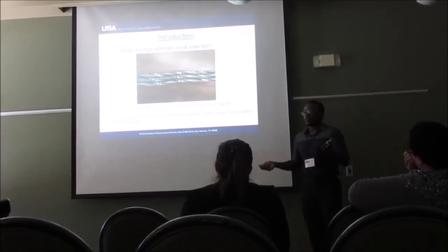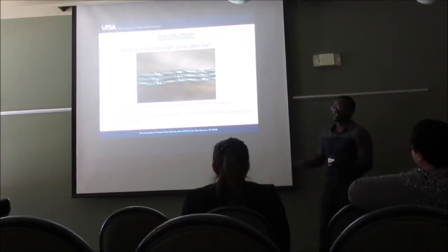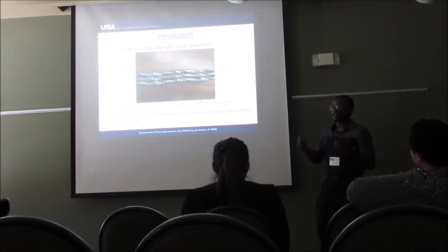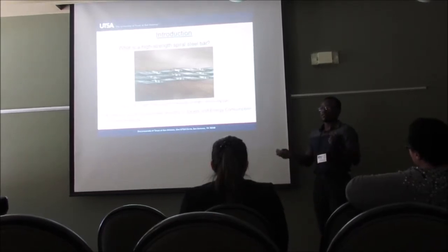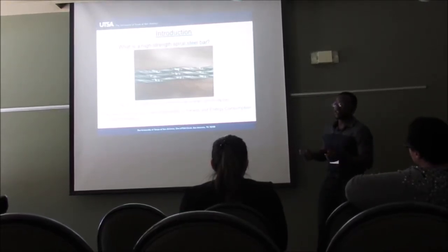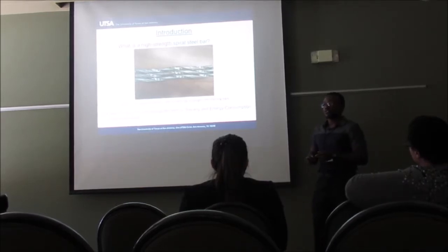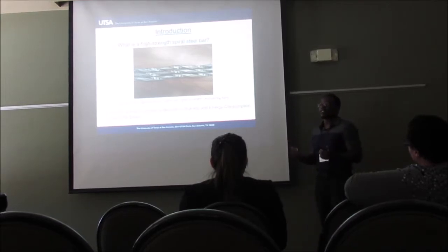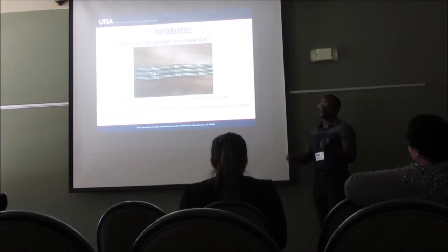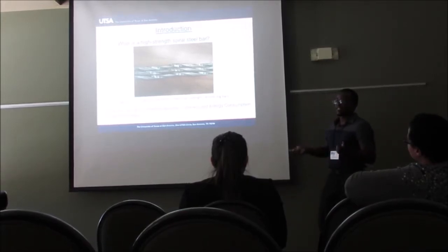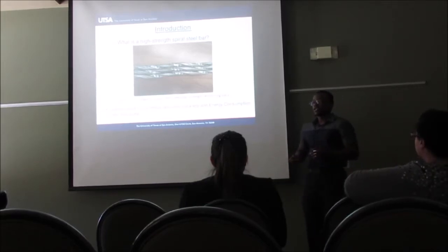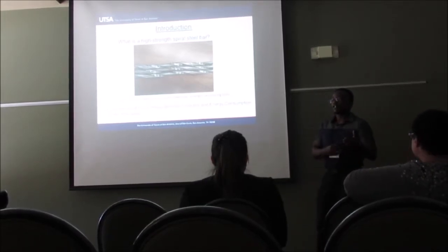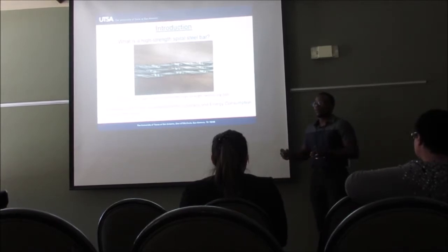There are very economic and environmental advantages to using high strength, mainly in the energy consumption. The steel bar is a big industry that needs lots of energy and demands primary resources, especially iron ore. So by using high-strength steel bar, we're able to use less material in our construction and still maintain the same safety. Also, there is limited data in building codes for concrete. There's data for regular conventional bars, but no one has really explored what to use for high strength in reinforced concrete.